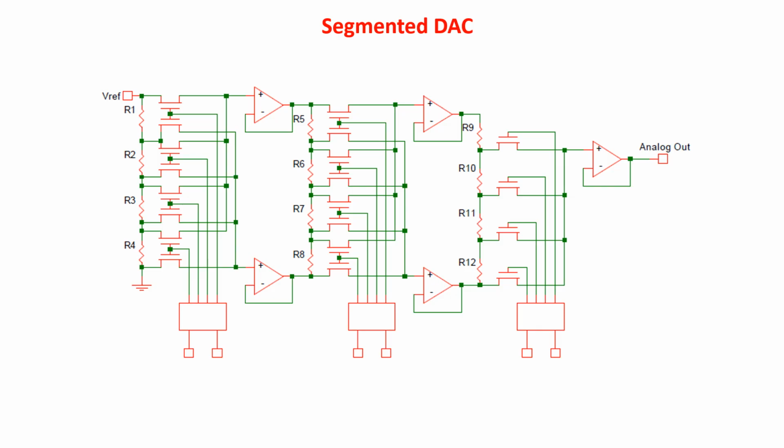A 6-bit number has 64 different combinations, so we can divide our reference voltage by 64, getting our minimum voltage range, or our maximum resolution. For example, if Vref is 8 volts, the minimum voltage sample is 0.125 volts, so the output voltage will have this maximum resolution. The output voltage values are multiples of 0.125 volts between 0 and 8 volts. Other values are not possible.